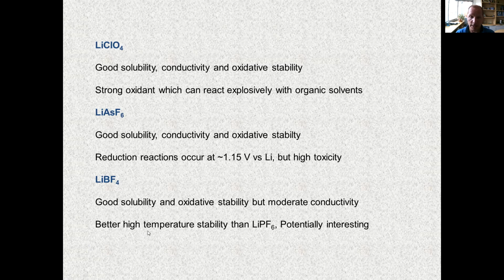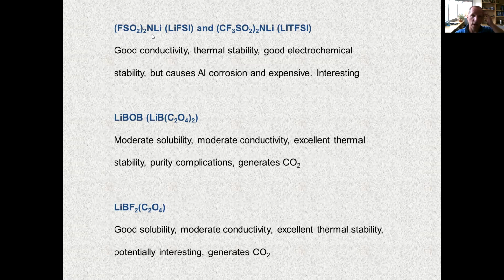It does have better high temperature stability than LiPF6. It's a very potentially interesting salt. And especially right now, there have also been a lot of studies done for high voltage applications where LiBF4 shows significant promise for use as a salt for high voltage cathodes. So as I said, LiFSI and LiTFSI are two of the more recently developed salts. They've got really good conductivity, very good thermostability, and good electrochemical stability.